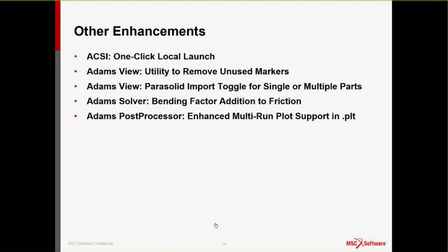So here, it's now enhanced to handle multi-run plotting. There's an option you can toggle on to say, hey, this was a multi-run plot. And so please preserve the coloration and the line styling that I've chosen, in the order that I've chosen it, so that every time I want to recreate these multi-run plots, I get the same line coloration and styling that I'd set up initially. The PLT file knows to look for multiple analyses of the same quantity in this case.